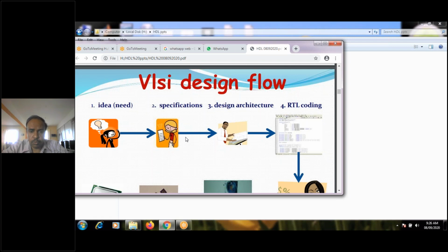So in data flow, we are just writing the code with respect to the connectivity between inputs and output. In case of behavioral description, you are writing the code with respect to the truth table. Next one is structural description. In case of structural description, mainly it describes the connectivity between the gates. Getting? So if you are showing the connectivity between the gates, basically you are explaining the structure of a particular electronic circuit, right? So this description we'll discuss in detail afterwards.